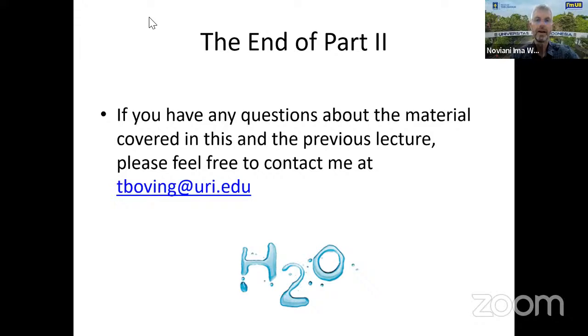Thank you. Okay, good question. So you're absolutely right. If there's an influx of excess fertilizer into the groundwater from the surface, let's say a farmer spreads out magnesium sulfate or potassium nitrate, or ammonium sulfate, then with rain, the fertilizer will dissolve and slowly make its way into the unsaturated zone until it reaches the water table, the groundwater table. What you get is an increase in total dissolved solids, meaning the salt content of the groundwater is increasing,